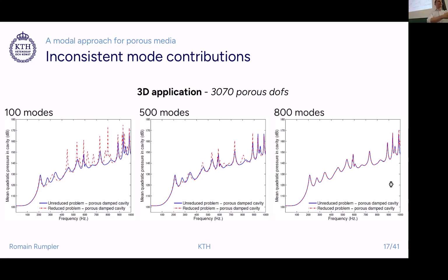By the way, we can go for the same criteria. I don't enter into those details, but essentially you need to take a sufficiently large eigenfrequency, so 2 to 3 times the highest frequency of interest, the typical truncation criteria that we have in component mode synthesis or modal basis approaches, in order to have a fairly good representation in the frequency range of your interest. I'm not getting into these details.